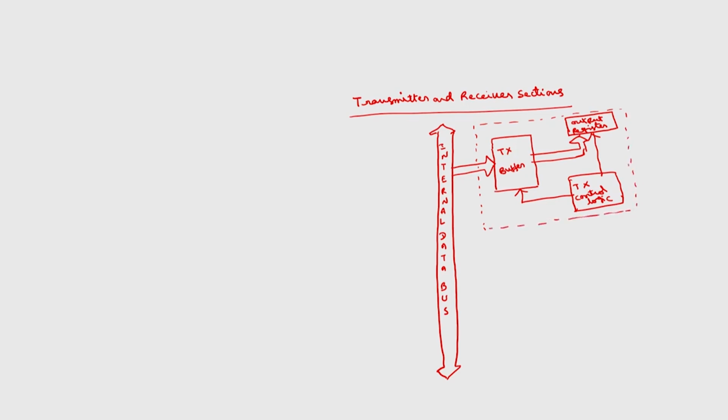So, what are the signals for this? We know that transmit data is one output signal, and there will be one input signal, the transmit clock, active low signal. Then transmitter empty, and then we have transmitter ready. So, these are the various signals available for the transmitter section.